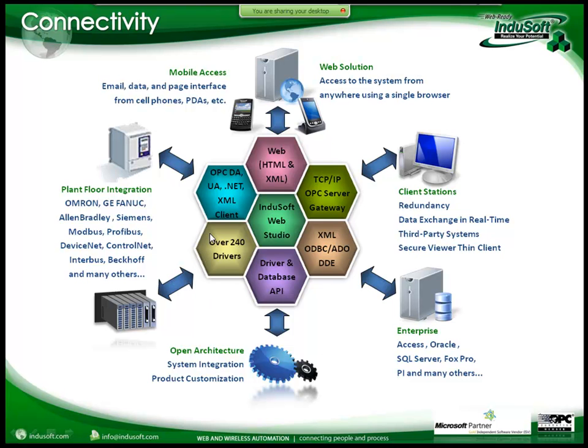All those drivers are installed along with the product. And in addition to the drivers, we also install the OPC clients for all the major OPC specifications, including OPC DA, XML, .NET, and OPC UA. InduSoft was the first company to release an OPC UA client, not only for PC platforms, but also for Windows CE.